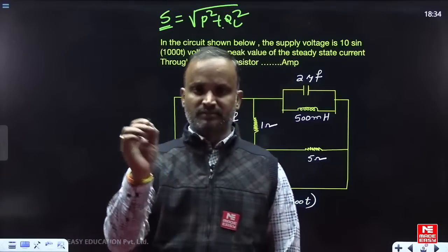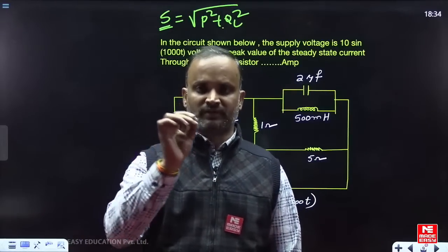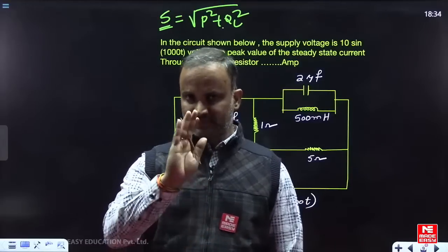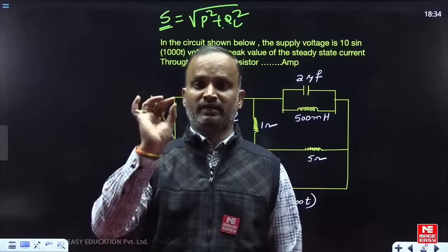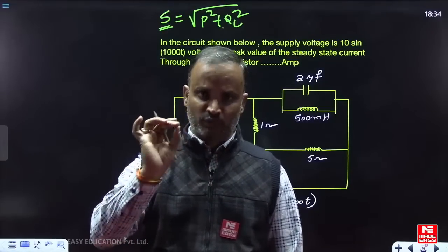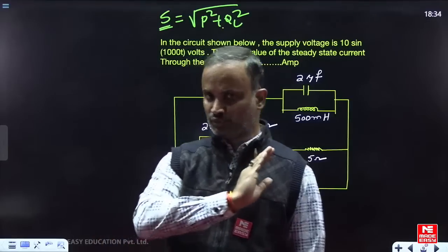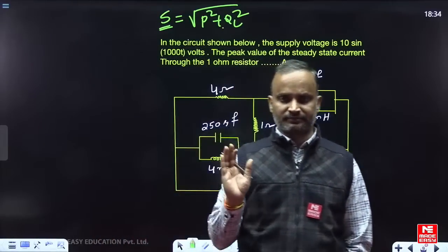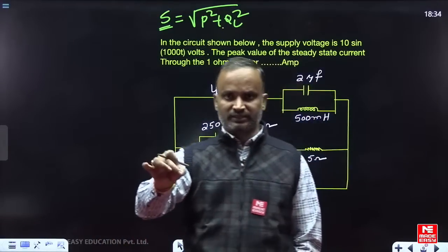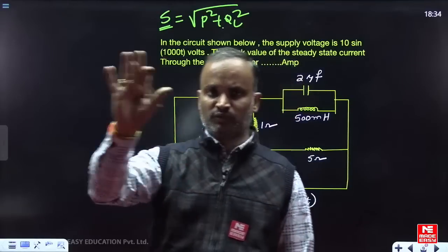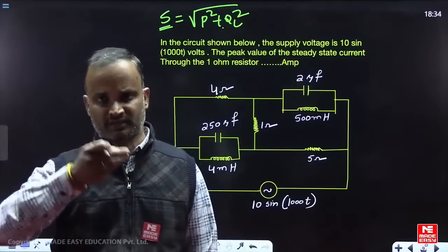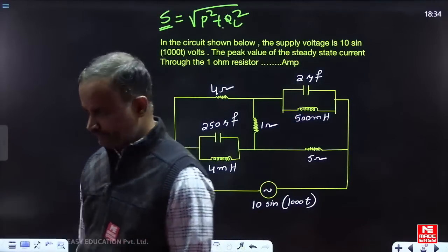In the questions, they simply give statements such as find the power in the network. If the statement given is find the power in the network, by default every time we go for the respective active power only. Don't go for the reactive power or the apparent power. If reactive and apparent are specifically mentioned, then only go for the inductive reactive powers or the respective apparent powers. Okay.